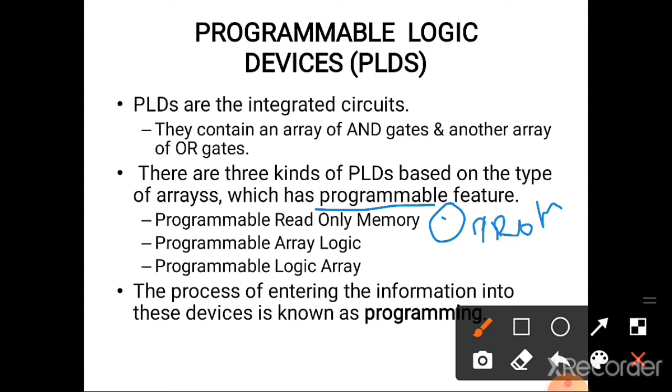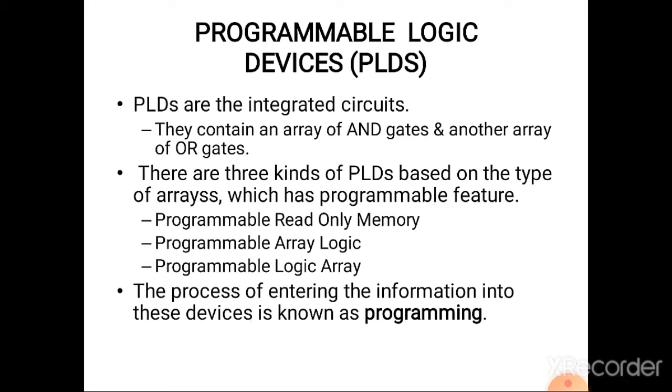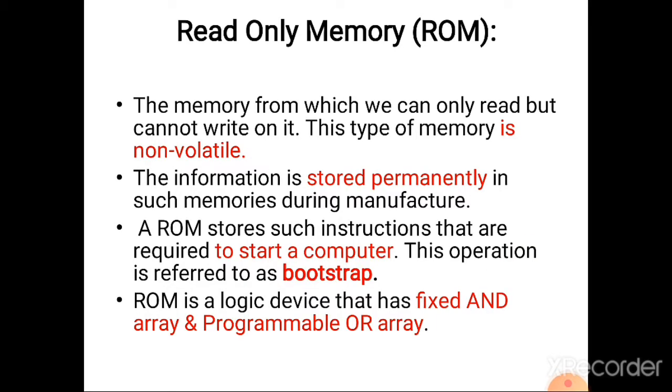There are three types of PLDs. One is PROM, the second one is programmable array logic, PAL, and the third one is programmable logic array, that is PLA. These are integrated circuits containing OR gate arrays and AND gate arrays, and we can enter information into these devices through a process known as programming. So the process of entering information into these devices is known as programming.